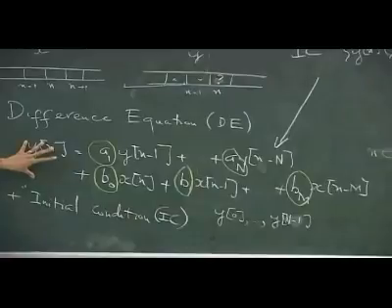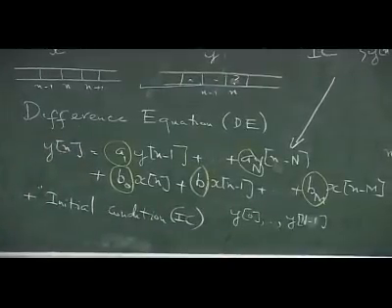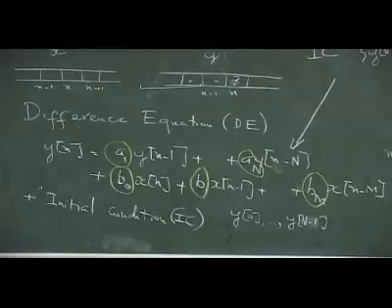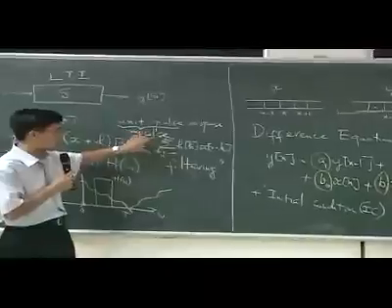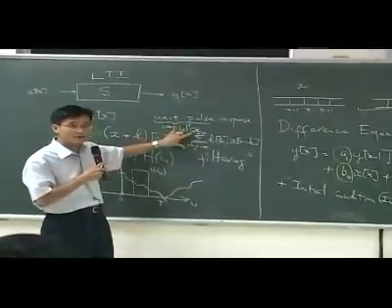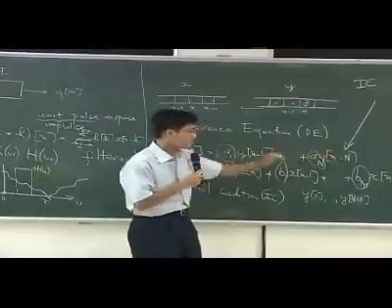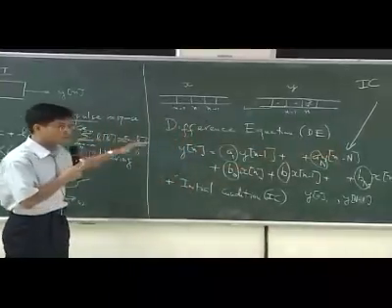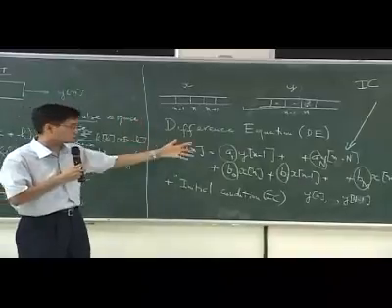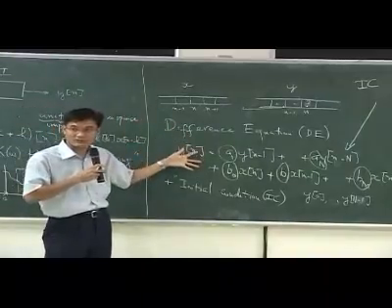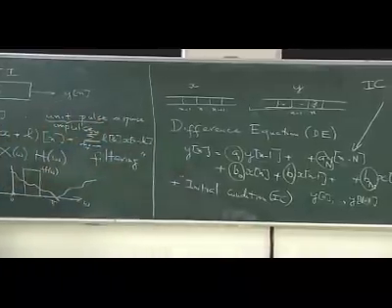Okay, is that clear? Let me repeat again. This convolution operation is only good for mathematical analysis. For actual implementation, you need either a finite number of terms, that means you only have this, or, if you want an infinite number of terms, you cannot choose just any infinite number of terms. You have to choose something that satisfies this form. Okay? So that will be two classes of filters.